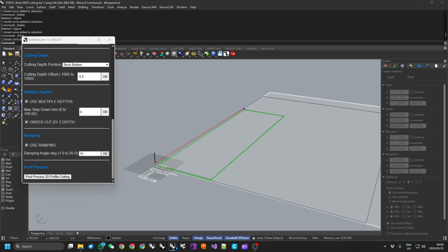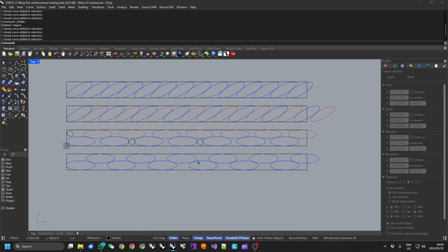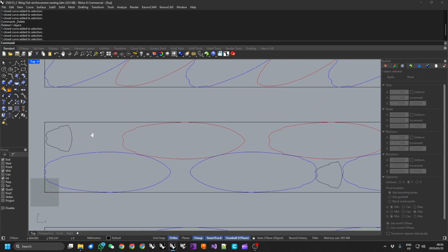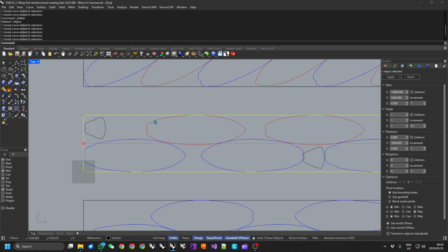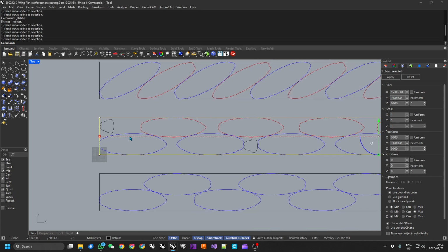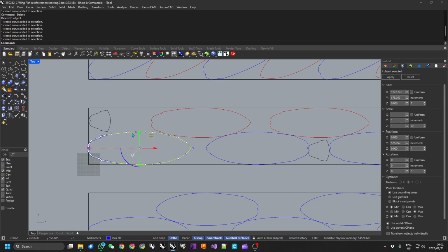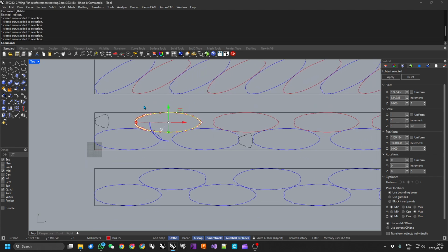But I've also been looking at how I'm going to nest up and how I'm going to cut the laminate for this particular project. What I have is a roll of basalt fiber, 15 meters of basalt fiber, that's 1 meter wide. We're going to need 2 layers of this material, top and bottom, and I want staggered, overlapped joints. So the blue outline that you see here is actually 50mm wider than the silhouette or outline of the surfboard, and the red line is 25mm, and that is for our ability to stagger the laps around the rails.